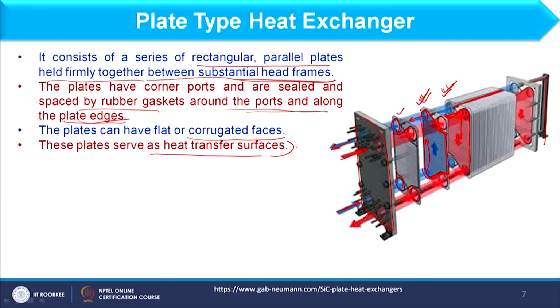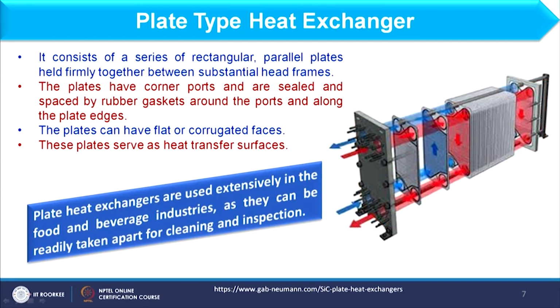Okay. So, this point we have already discussed. As far as the utility of plate heat exchangers is concerned, these are used in the food and beverage industry, as they can be readily taken apart for cleaning and inspection. Now, as I have told you, the two plates are very compact, very close to each other. It means it has a very high tendency of scaling. To avoid that, plate type heat exchangers are usually used for clean fluids, not fouling fluids. So, that is the main point about plate type heat exchangers.